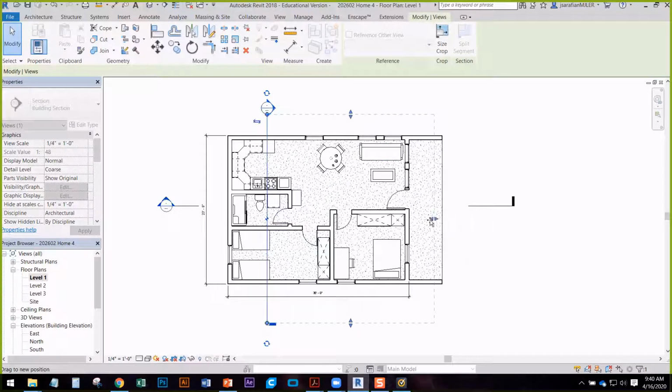This is the view box. So this is how far your section will look, right? It'll automatically grab the building for the most part. If you're seeing too much, sometimes you're grabbing information that you don't need. You're going to have to adjust this. Same with when you make elevations, you'll have to adjust how far the drawing itself is looking, and that's the extent here. Same with the sides. If you're grabbing too much information that you don't want to include, you can adjust that here.